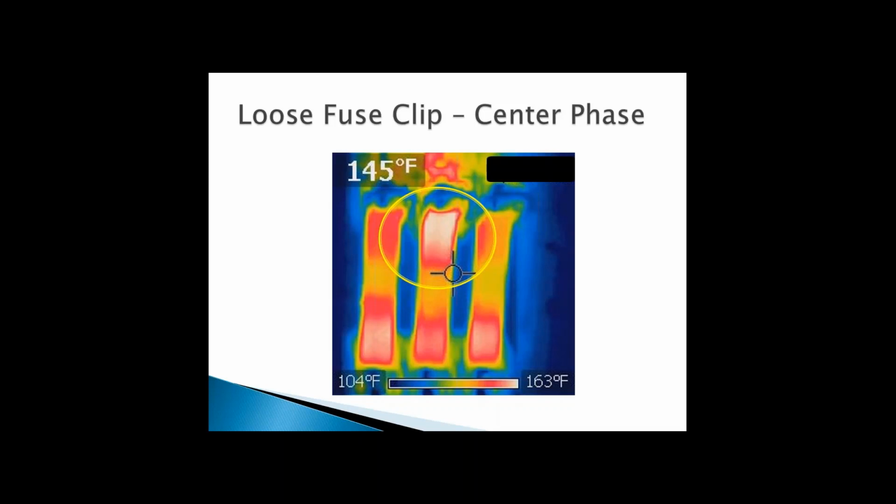This is a loose fuse clip scenario from a three-phase disconnect that I encountered using another manufacturer's piece of equipment. Just to show you that you shouldn't make assumptions just based on the image that you see. You have to perform a secondary test to verify your assumptions.